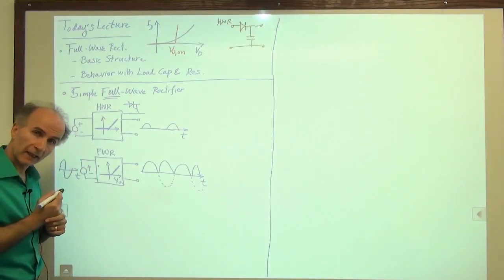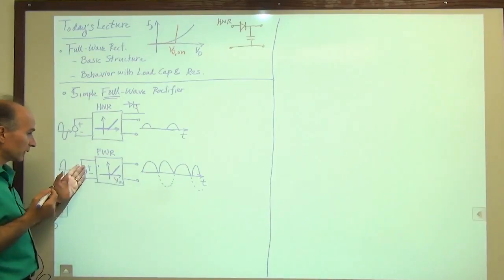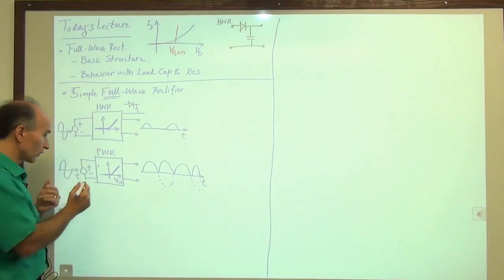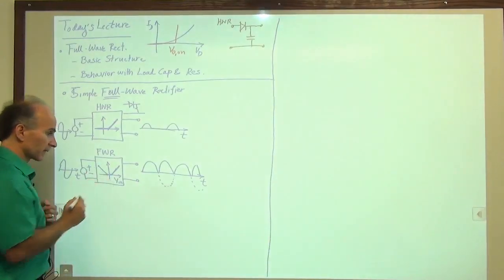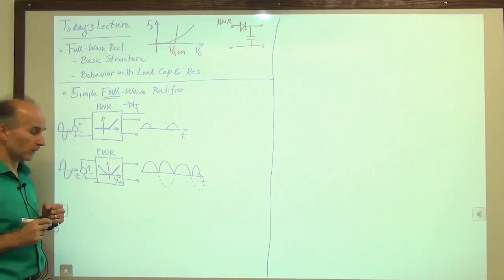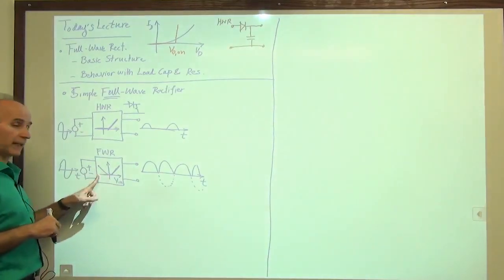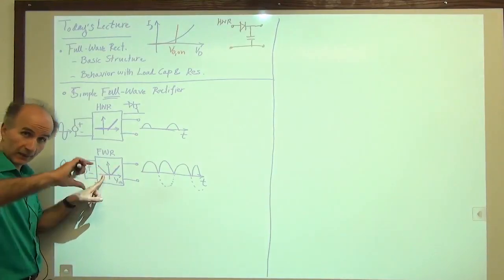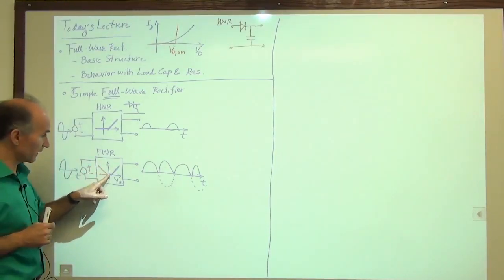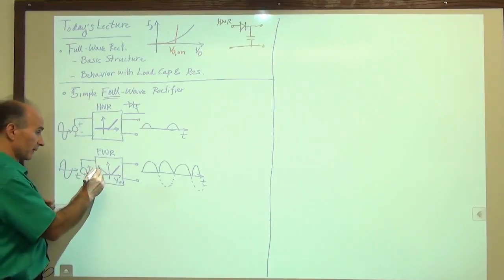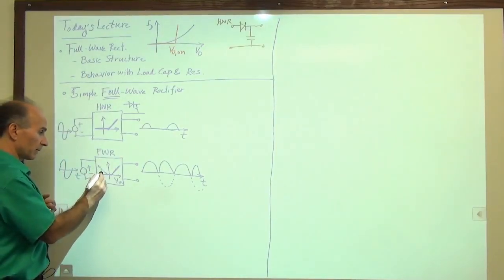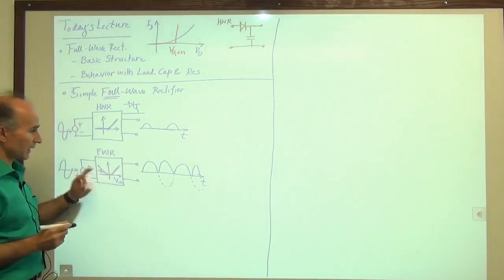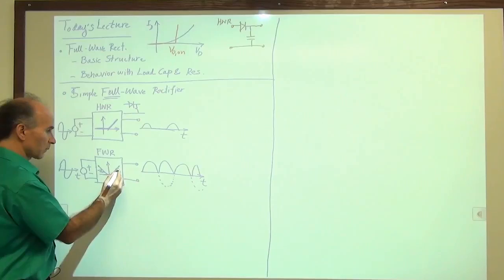So what we are thinking is that the input-output characteristic of this full wave rectifier should be something like this. Right? We see that if the input is sufficiently negative, we generate an output which is the same as the input except that it's flipped in sign. The slope is still -1. Maybe, right? We don't know yet, but maybe -1. And then this side is the same as before, so the slope is +1.